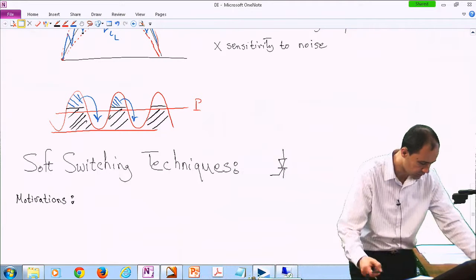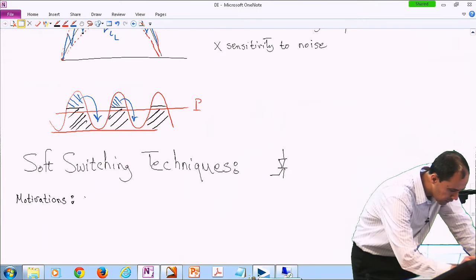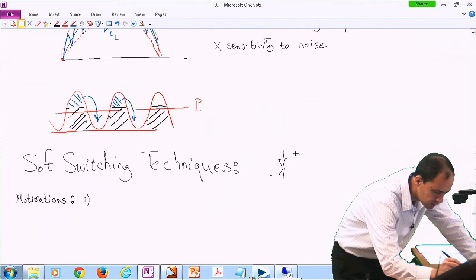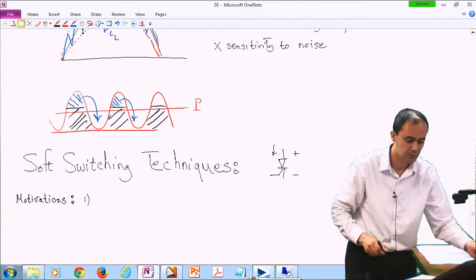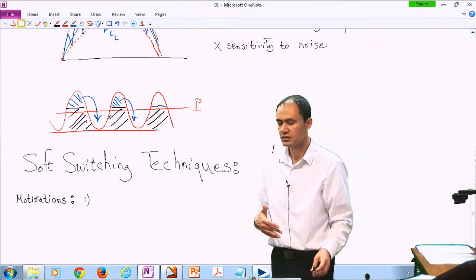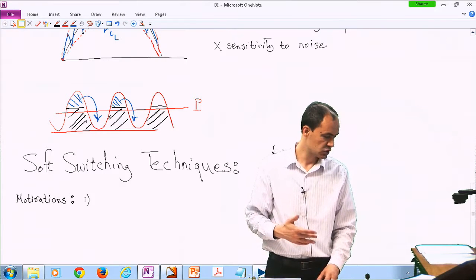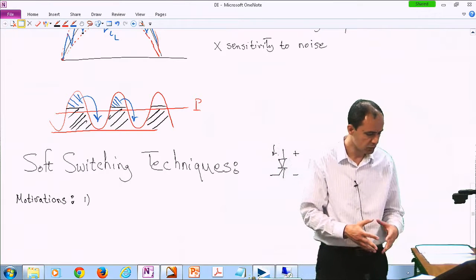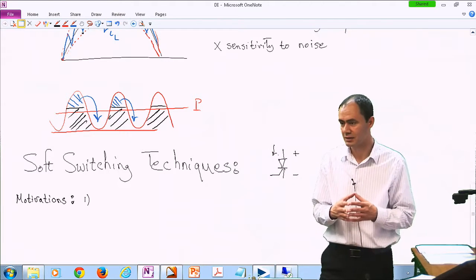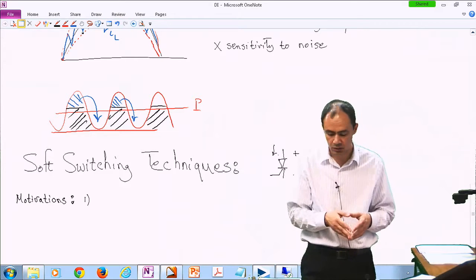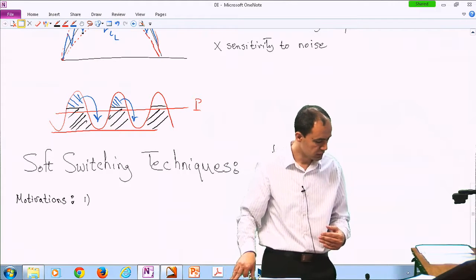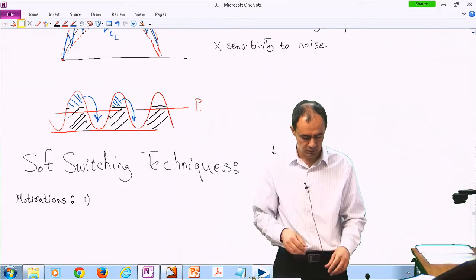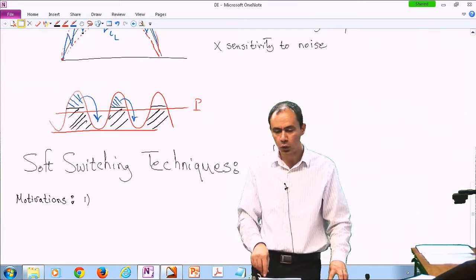We don't care much about how they function, but the major problem with SCRs was, if you look at the voltage of this device and the current of this device, if the variations of the voltage on the device when the device is off are so rapid, the device false triggers itself, so it turns on. Also, if the variations of the current passing through the device while it is on are so quick, you may have some localized heating within the silicon device, and locally burn the device.